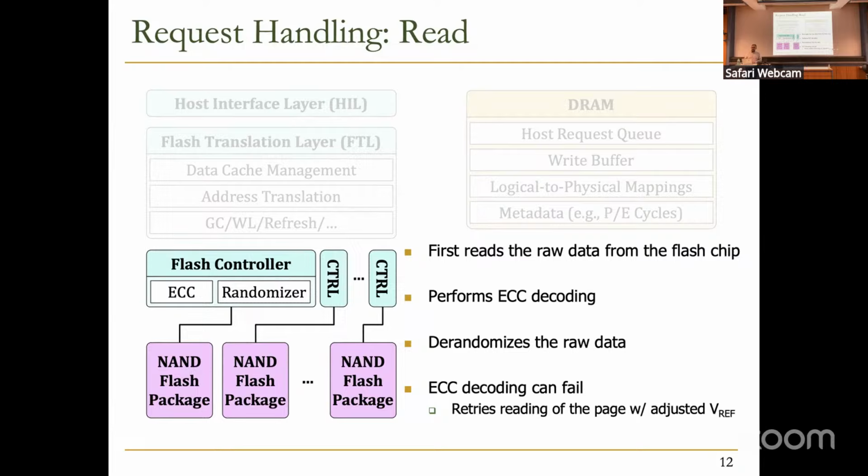Yeah, that's one thing. In modern SSDs for enterprise systems, that DRAM is actually large enough to keep all the L2P mappings. But in the end, we need to write it back to the flash chips. But in mobile SSDs, for example, we don't have that large DRAM, and that's why the DRAM is just trying to cache a part of the L2P, depending on your access patterns. There are works along that line, DFTL, for example, that discuss how we can cache the FTL. Yeah, because otherwise you need to do a double access.